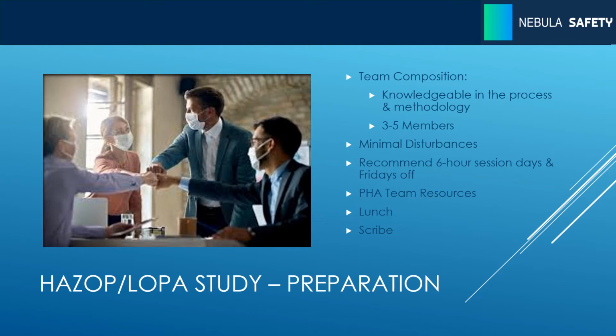But I've also found having other subject matter experts, maybe not full-time, but rotating equipment specialists, subject matter experts on toxics, on release case analysis, things like that, really flesh out the team and let you perform an accurate study. As I mentioned previously, the HAZOP itself is a brainstorming session. So it, of course, is subject to the experience of the team at hand. So you really want to make sure, if you want to do a successful PHA that really matches what can happen in the field, then of course you really want to make sure you have personnel who can adequately perform that task.